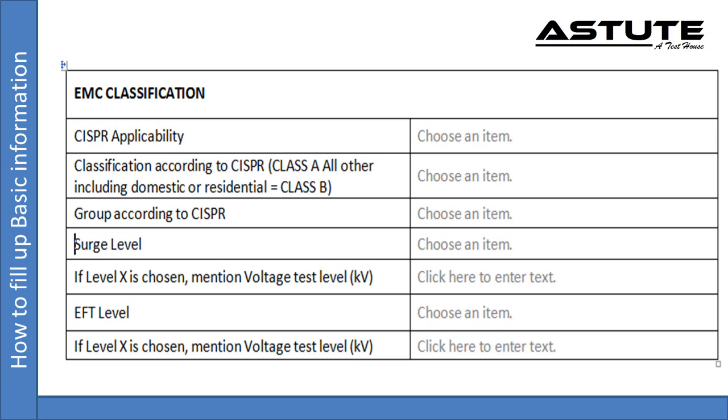Outside the electronic equipment, there is no widespread earthing system, exposed plant. The interference voltages due to earth faults, currents up to 10 kA, and lightning, currents up to 100 kA, can be extremely high. The requirements of this class are covered by the test level 4.